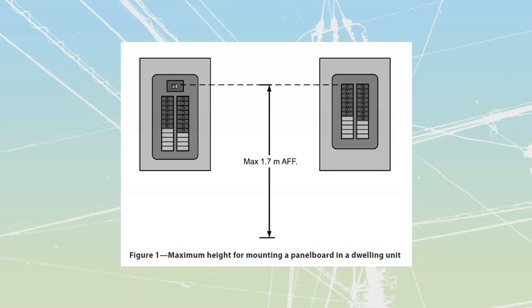The CEC actually will give you a bunch of different places that they consider to be undesirable for panel boards. They give you bathrooms, clothes closets, coal bins. Who has one of those anyways? But a bunch of places that are either damp, filled with combustibles, that would be like a coal bin, or going to be really warm. If you stick inside of a clothes closet, you have coats and stuff up against there, you're going to trap a lot of heat in there, you're going to have nuisance tripping, and potential for fires as well, because you cannot just effectively bleed that heat off.